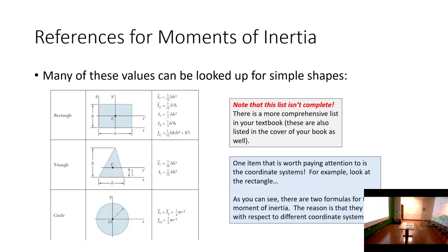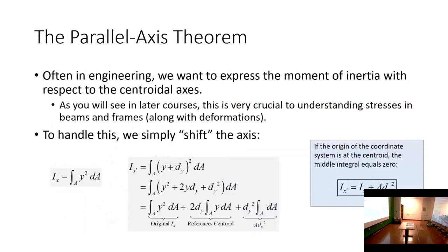With me so far? Okay, now what I'm going to show you is the algorithm that we're going to use to compute the moment of inertia of a composite shape. If we talk about centroids, we had an introduction to centroids where we had to break out some integration and derive some formulas. But ultimately, if we really wanted to roll up our sleeves and actually compute the centroid of an engineering part, we didn't use the integration. We took the part and split it up into a series of simple shapes: some rectangles, some triangles, some circles, some semicircles, and handled each of those parts one at a time.